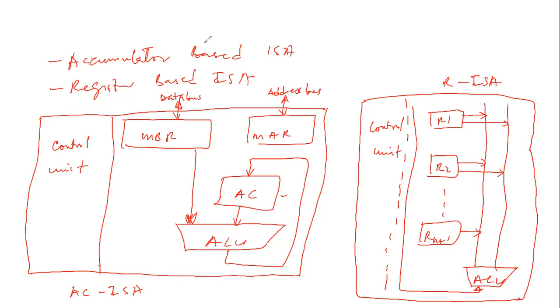So the data bus connects the CPU to the outside memory, and it is bidirectional. It is used to move data in and out of the CPU. Now you also see that the memory address register interfaces via the address bus. It contains the address of an instruction or data found outside the CPU, that is, in the memory. So the address bus contents are found in the register MAR.